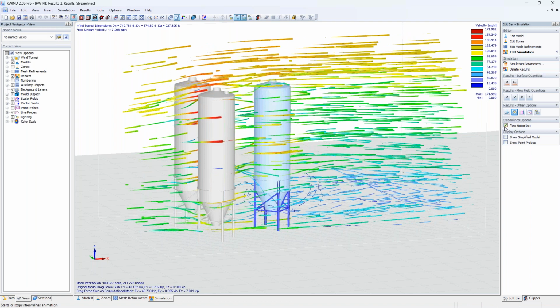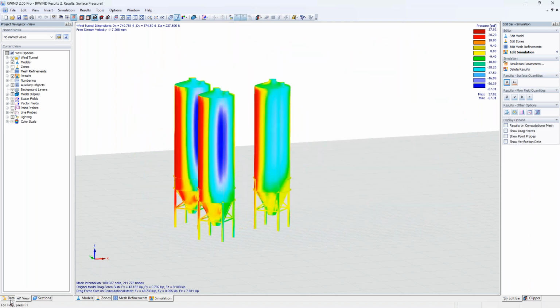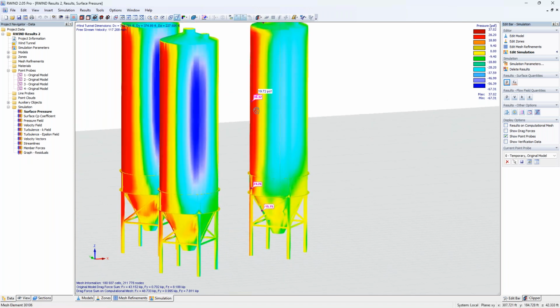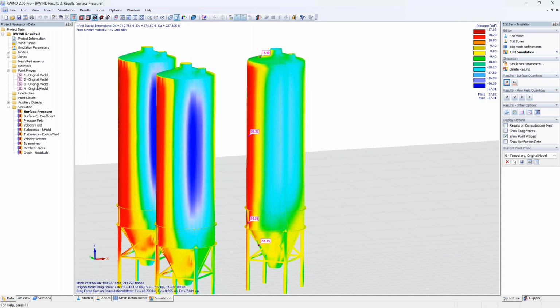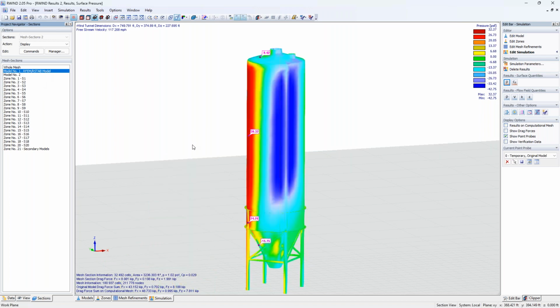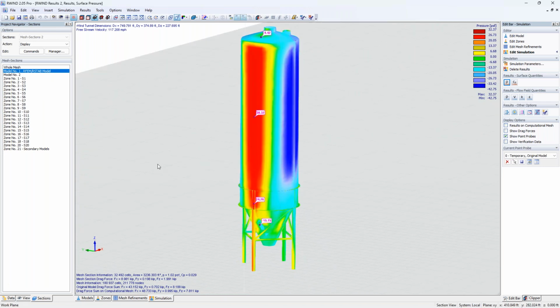So going back to the pressures here, under the data tab, remember how we have just set those points back in RFEM for the experimental data. These are now inserted here as point probes. So you can see those 4 point probes given to me at those particular locations, and they're available here within my navigator. And under my sections tab, I'm going to go ahead and only activate here the RFEM model so that we don't need to worry about the view of those additional IFC objects.